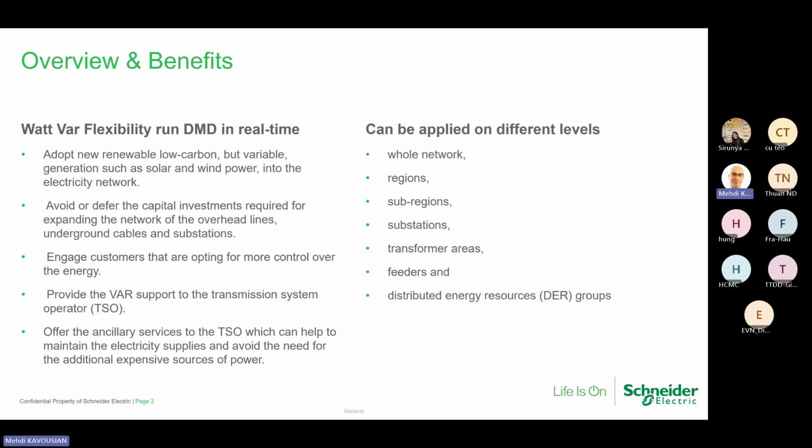Your transmission company tells you, all right, keep your loads below this value because I have constraints, I have problems with generation. They sometimes give an order to keep it below this. But in all such cases when they order this, they do load shedding. They drop some loads from some customers to mitigate to below that limit, right? Now, if you have flexible load, we can say, okay, put more solar or put more battery as a generation, and we can mitigate from the top.